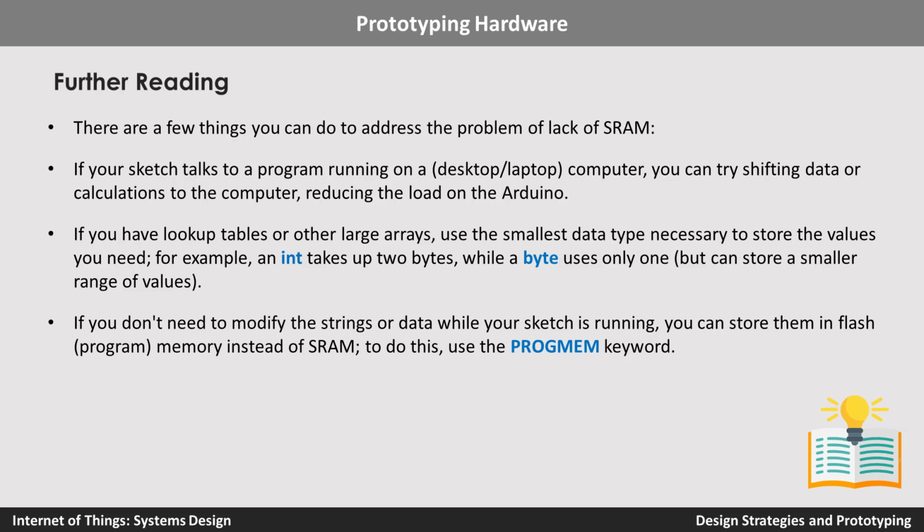Also, if you have lookup tables or large arrays, you should use the smallest data type necessary to store the value. For example, an int takes 2 bytes, and if you declare a byte, it only takes 1 byte. Of course, if you use a byte, that means you have a limited range of values you can store, but if that is sufficient, then you should not waste an int to store that.